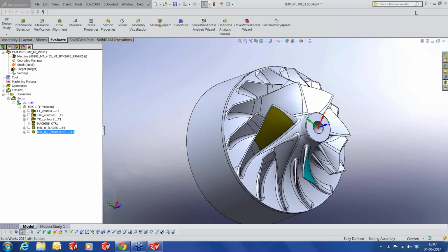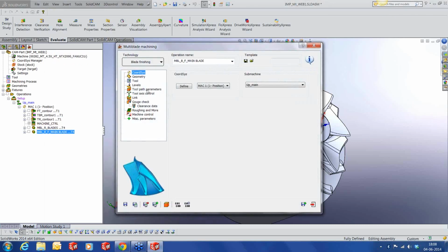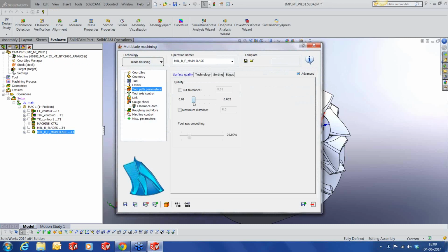The question somebody asked is, what is the tolerance that you could expect on the final product? Now, the toolpath tolerance altogether out here is set at 10 microns. So the toolpath is going to be plus minus 10 microns. And obviously there are tolerances on the machine, the tolerances for holding, the tolerance for the tool. My experience is about 30 to 35 microns is the end result tolerance that you would get if you use 10 microns as a tolerance inside the toolpath.